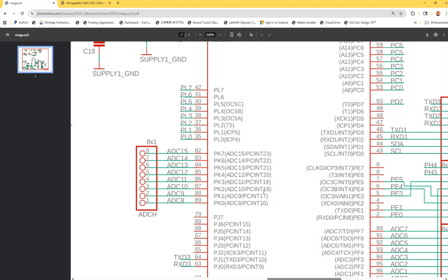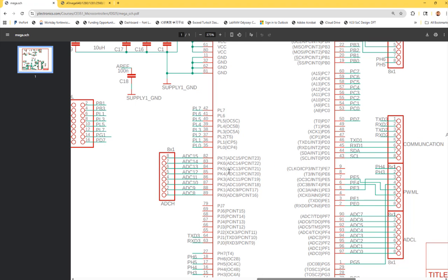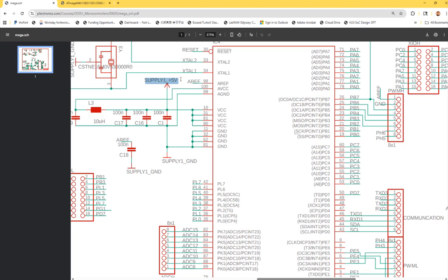And there's no regulator on it. Why? Because the USB cable, which is connected to the desktop, and your desktop, whatever the USB chip in there, they must have some sort of regulators, right, to stabilize it. So you don't have to worry about that 5 volts. You can trust that 5 volts stable. So that powers up your whole thing over here,